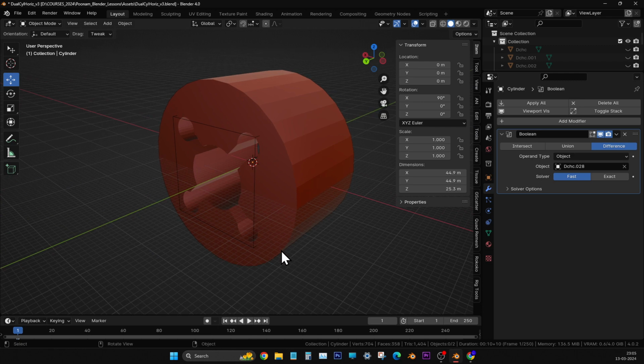What you are saying is we can do the remeshing, because without remeshing, when we do the shading, it won't look good. So for that sake, we have to make it a workable model. That is quadrilateral. Once we make it quadrilateral, the shading or whatever we are going to apply will be nice.